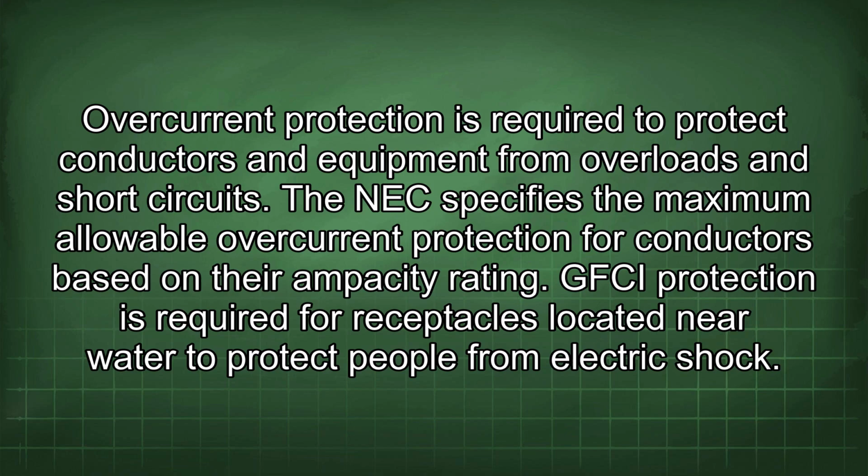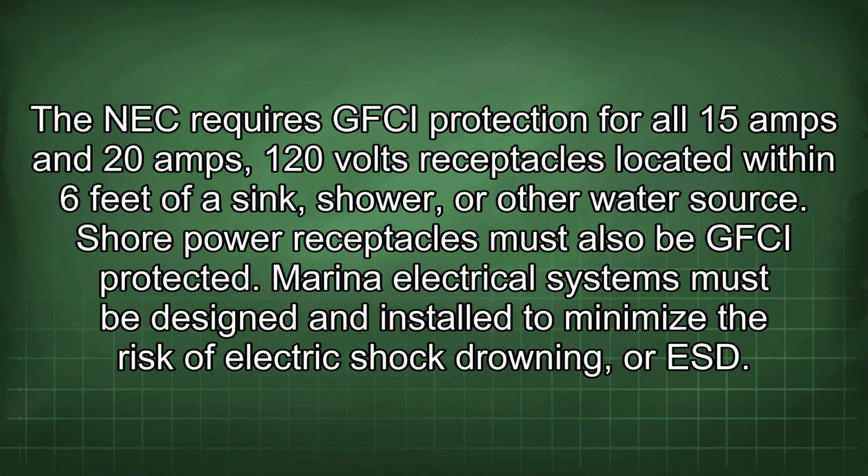GFCI protection is required for receptacles located near water to protect people from electric shock. The NEC requires GFCI protection for all 15 amps and 20 amps, 120 volts receptacles located within 6 feet of a sink, shower, or other water source. Shore power receptacles must also be GFCI protected.